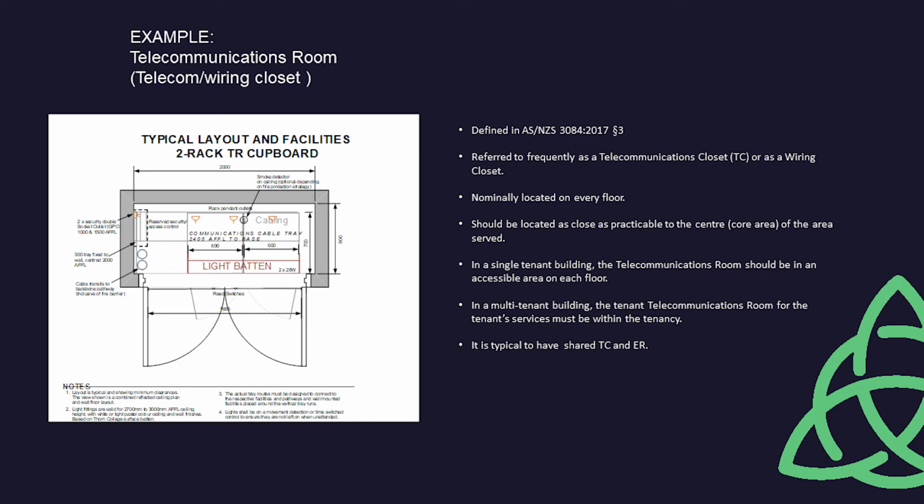Additionally, avoid locations which are close to sources of electromagnetic interference, locations that are within the 430-volt contour of an earth potential rise hazard zone, and using existing walls, ceilings, or floors that contain asbestos that may require removal or containment. Again, this restricts future expansion. The rooms must guarantee 24/7 access for the required staff to maintain the equipment.